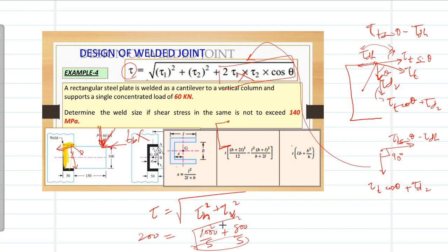In the case where there is a beam in which the welds are non-symmetric, the problem becomes difficult, and that's why you have to consider all these stresses based on all the different kinds of loads. It's very important for you to practice these problems. Please practice. Take different cases, take different angles of forces, and see what size you come up with. The size again should vary from 2 mm to 30, 40 mm. It could not be 0.1 mm, and it could not be 100 or 200 mm.